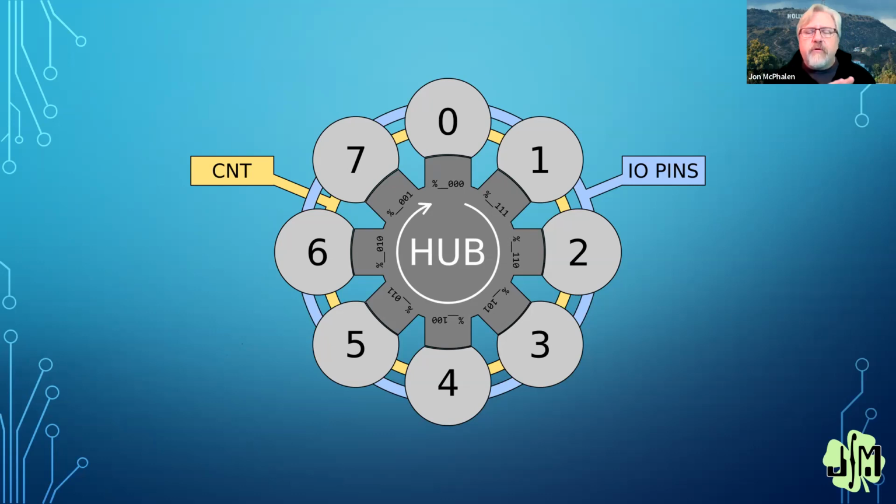I took a very simple Spin program and ran it on a P1 at 80 megahertz, which is kind of the standard P1 speed. I moved that code over to the P2, made whatever language adjustments were necessary, but no efficiency changes, just the language naming conventions. I set the P2 to run also at 80 megahertz, and I measured the speed differential between the two. The P2 running the same code at the same clock speed was 16 times faster than the P1.